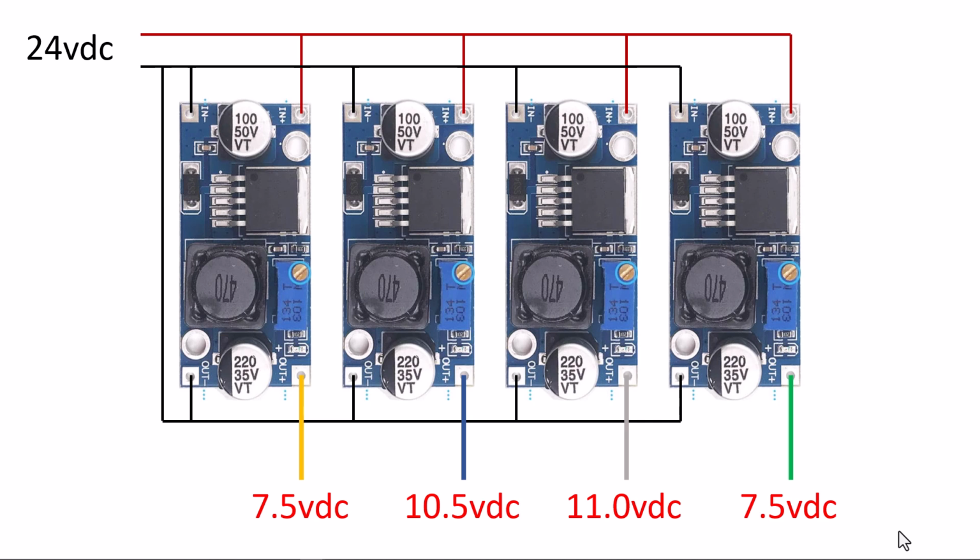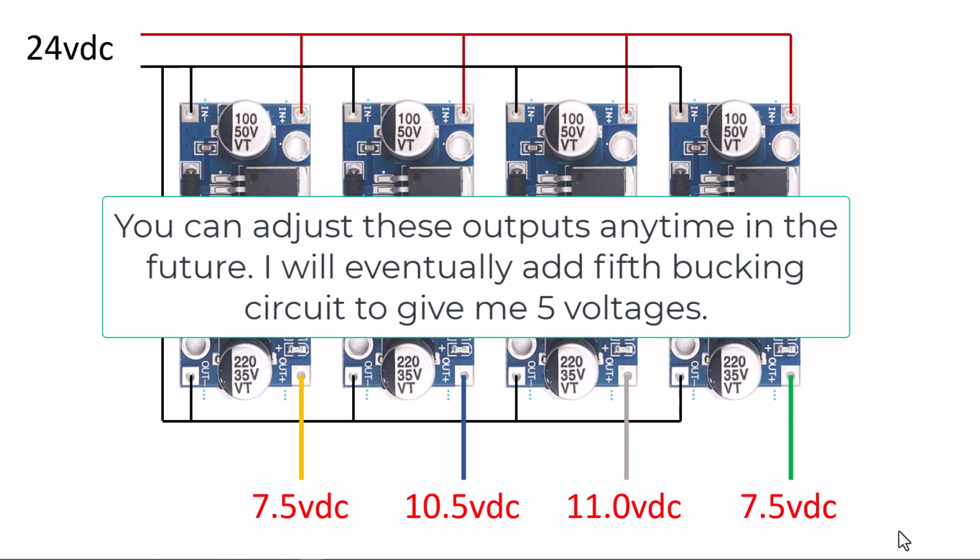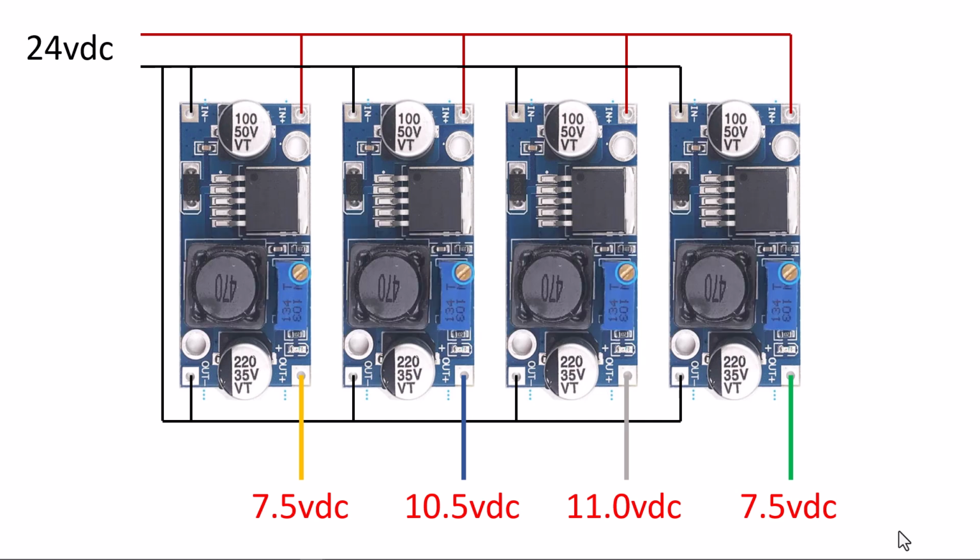Now you're looking there and you're saying, well, there's 2 of them that are 7.5. And the reason that I have a 4th one, and I'll explain it in more detail later, is that as you're increasing the voltage and the locomotive's going faster, doing other features, if you decide to go back to a lower setting, there's a certain level of hysteresis. In other words, if something happened when you went from 7.4 to 7.5, and then it started doing something, that doesn't mean if you go back to 7.4 that it's going to stop doing what it did. It won't. There's some hysteresis.